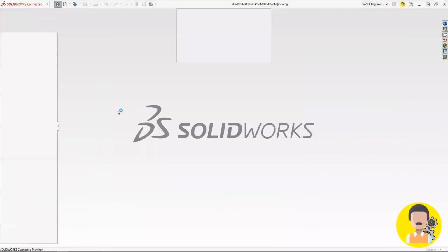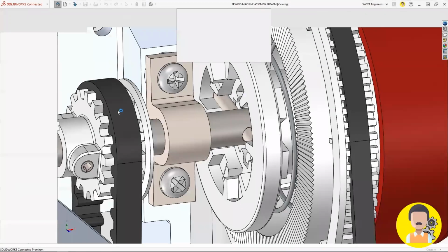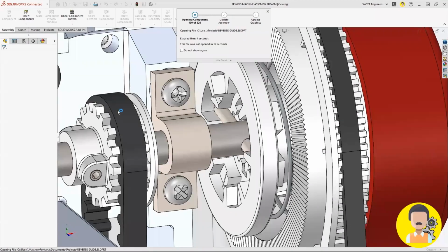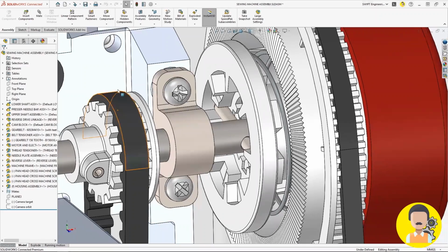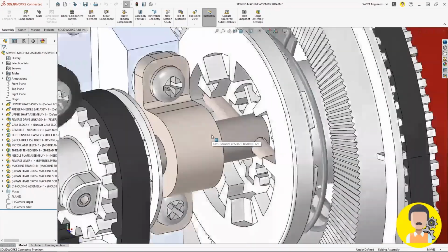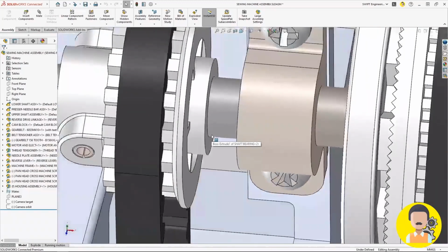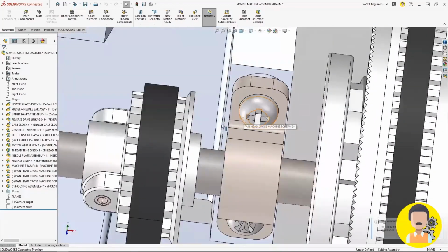However, switching over to Lucas, now when he opens that, he unfortunately doesn't have access to Jill's desktop. So when SolidWorks goes through its references and tries to find that file, it will go through that search routine. In his case, he had the old version of it somewhere in one of those 8 steps, so it just reverted right back to that old version. So both of them think that they've done something right, and now neither of them knows what went wrong. Understanding those file references could cut down on a lot of that back and forth and make sure that this is streamlined and done right the first time.